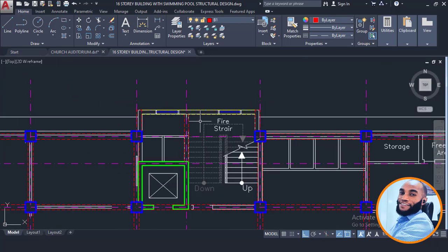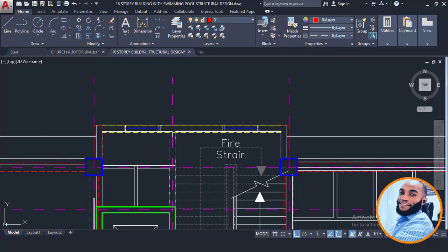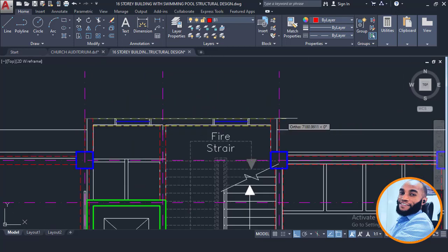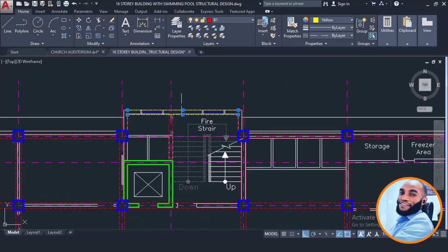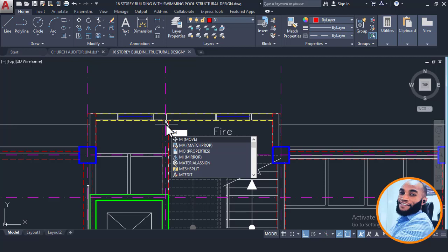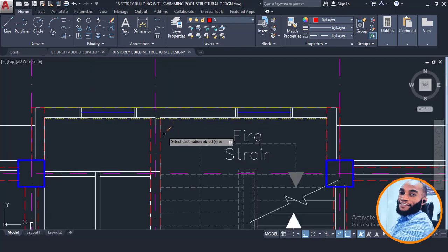Okay, so right now I'll have to confirm what is the length of this. So I'll confirm from here what is the length from this point of grid to the point of grid here, to check this beam length along this place here. This gives me 7 meters, which is okay. Now since this beam here is supporting this beam here, basically I'll have to make this other one a secondary beam 2, secondary here,